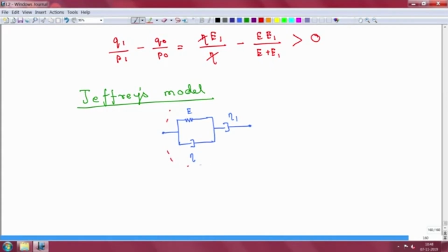This is obviously the Kelvin-Voigt body right here, right. So, when you apply a particular force, the displacement in this is going to be bounded, okay. But for the case of the dashpot, you cannot ensure that. So even for small finite forces, the dashpot will keep on increasing or keep on displacing. So this entire model will have a system level displacement, where the displacement will keep on occurring even for small forces, right? And that is reminiscent of a fluid, right? So this particular Jeffery's model is appropriate for viscoelastic fluids, and that is why this is also often known as Jeffery's fluid.